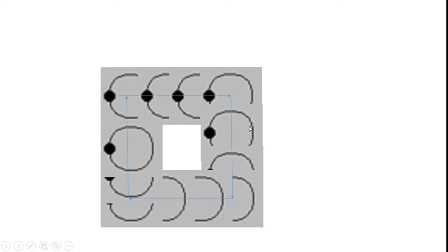Already I told you how we make the centroidal path. Then I offset the centroidal path with respect to the x-axis and the y-axis. From this, I get the new tool path for making an empty volume on the component face. The tool moves in the x and y directions, and from this we can achieve the empty volume.